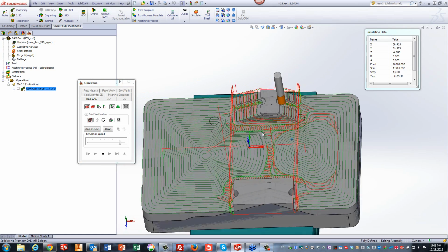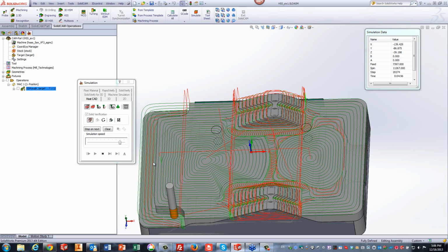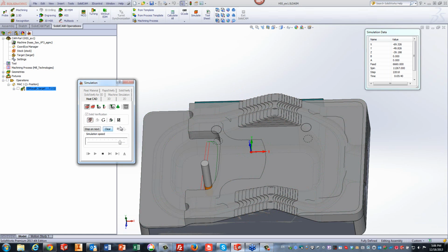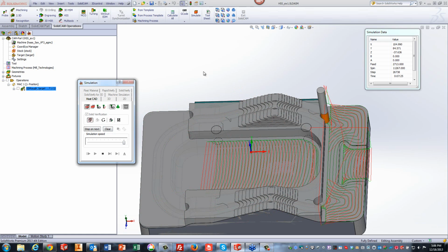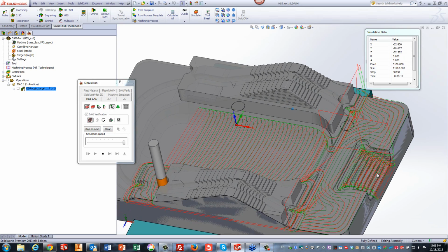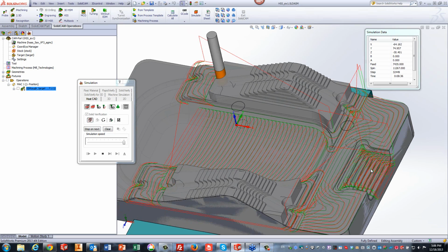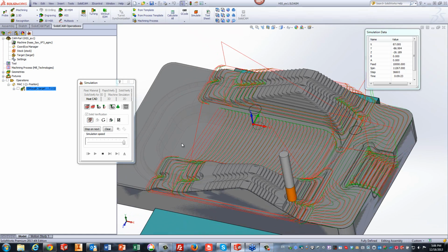Note also that as it finished the step, it's now worked up on these areas before going down to the next level. Now that it's finished this area, it's now going down and doing the next step as shown there. It does this all the way down to the very bottom, leaving us with the exact material that's needed for our finished cut. Note also that these steps here are also machined up there. It's finishing off this level up until here, and then it's going to finish off the next level after it finishes this side.